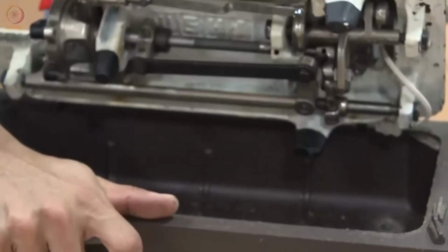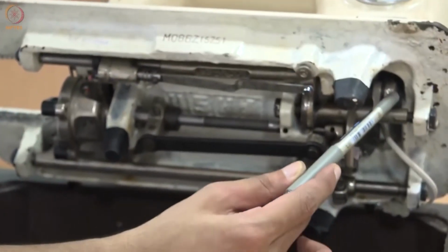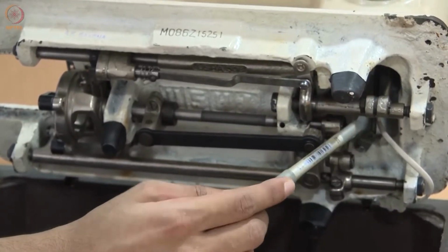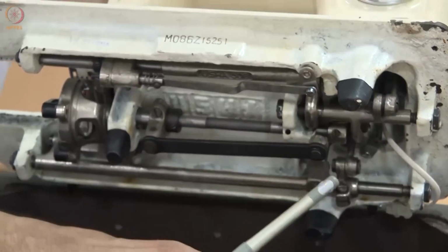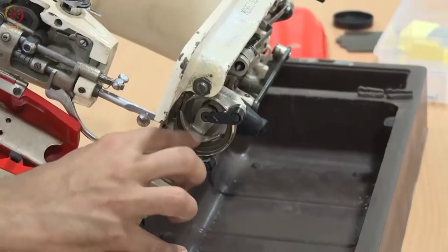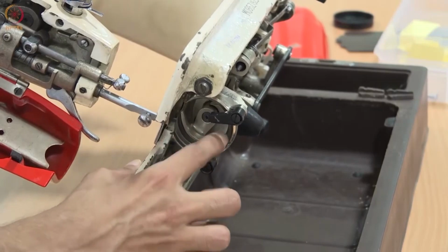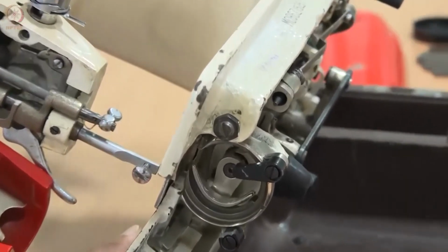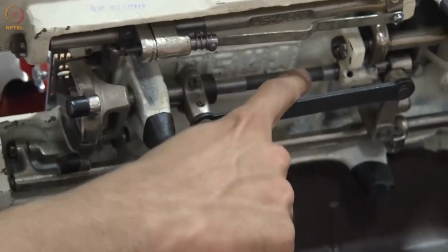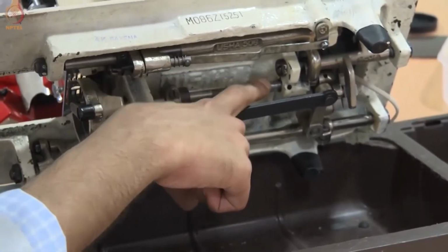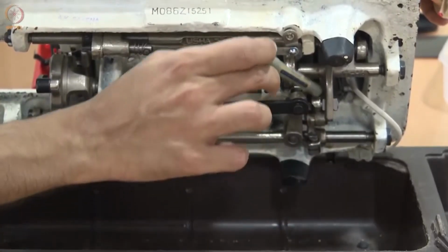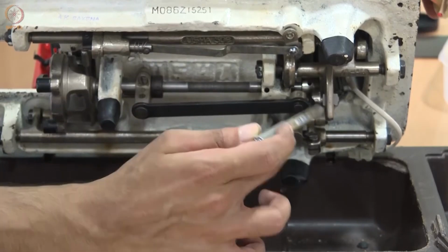Basically, this is the bottom part of it. You can see this oscillates another shaft here. I'll just briefly go through the mechanism without going in depth because a very elaborate treatment takes time. You can see this shaft, this bottom part basically oscillates. How does it get that oscillatory motion? So this is connected to a shaft here. And where does that shaft connect? It's connected to another crankshaft here.